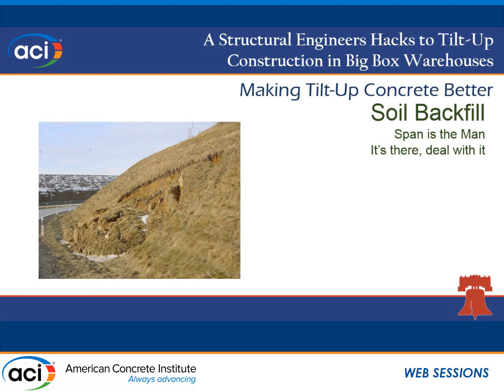I had a job recently I looked at that had a problem where they hadn't correctly dialed it in, and the soil deflected the panel about 1/2 inch to 5/8 of an inch at the base and about 2 inches at mid-height. And that was just from the soil over time pushing and pushing and pushing out the wall. It broke the dowels off, which was the issue.